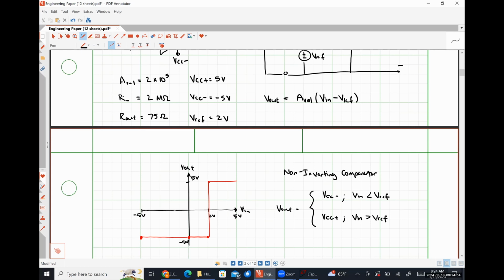So this is something that's used very regularly to do power measurements and all of that kind of stuff using microcontrollers, because microcontrollers typically can't take large input voltage ranges. So if we were trying to use a microcontroller to, say, measure the power factor at which a load that's connected to an outlet or something like that is operating at, we couldn't simply just plug our input voltage of 120 volts AC into our microcontroller.